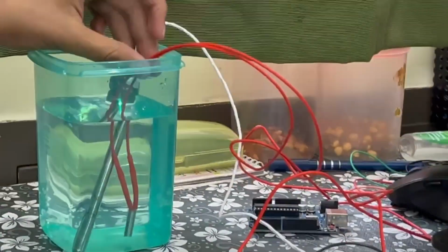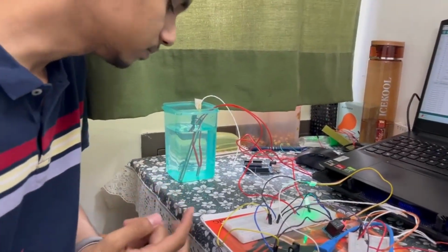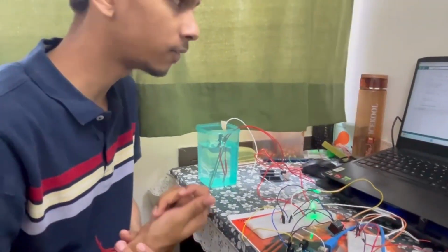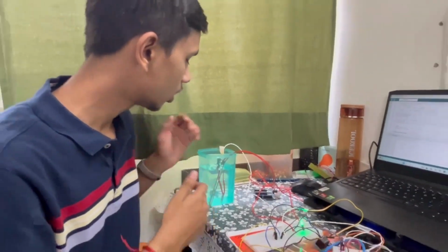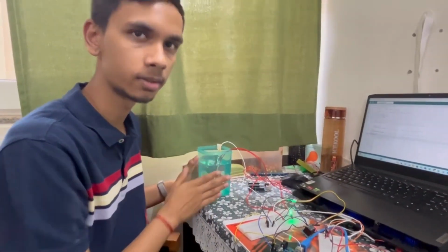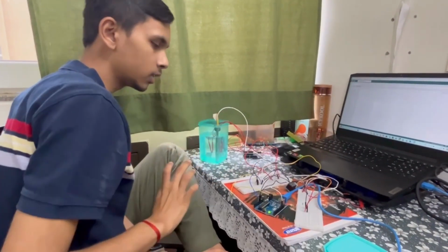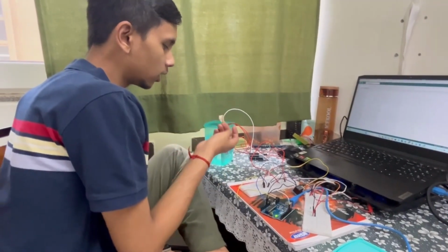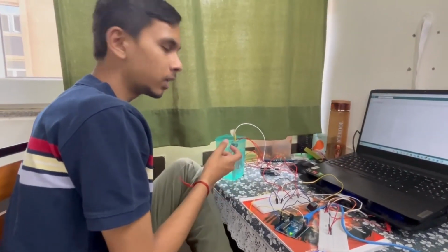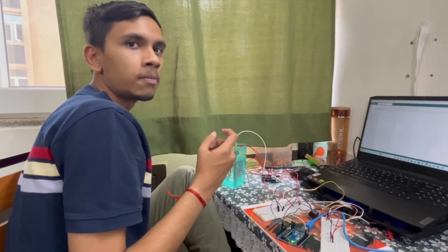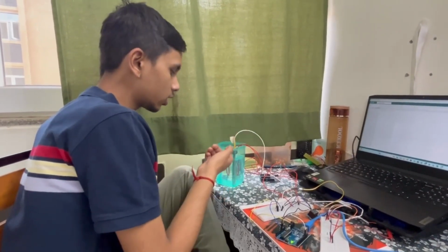Now the heater will start heating up the water slowly, and after some time we will get the system at a much higher temperature. So we can see that the temperature is 36.04, and thus, as we have shown, if the temperature goes above 35, the heater will stop. After heating, the heater turned off at 35, but as it was very hot, the temperature we are showing has gone to 36, and it will gradually reduce.